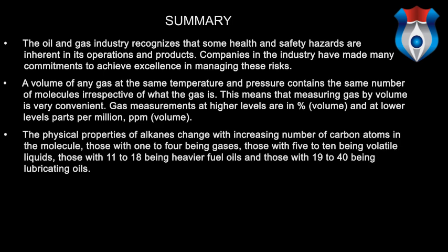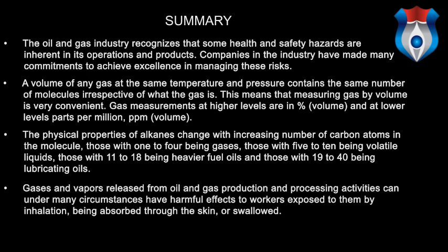The physical properties of alkanes change with increasing number of carbon atoms in the molecule, those with 1 to 4 being gases, those with 5 to 10 being volatile liquids, those with 11 to 18 being heavier fuels and oils, and those with 19 to 40 being lubricating oils. Gases and vapors released from oil and gas production and processing activities can, under many circumstances, have harmful effects to workers exposed to them by inhalation, being absorbed through the skin or swallowed.